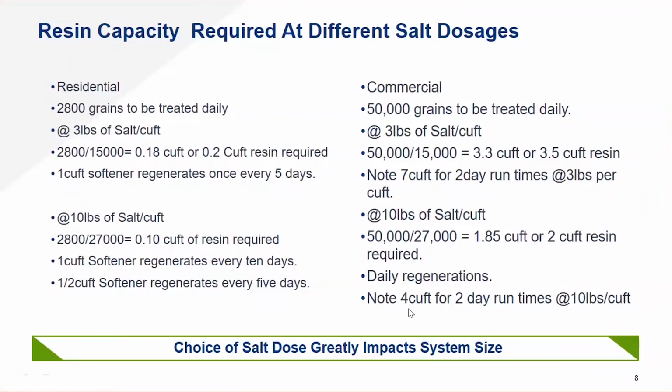So lots of ways to tweak how often we run. But this is how we get to the capacity of our tank. So when you're designing a system, your salt dose plays a critical role in the capacity.